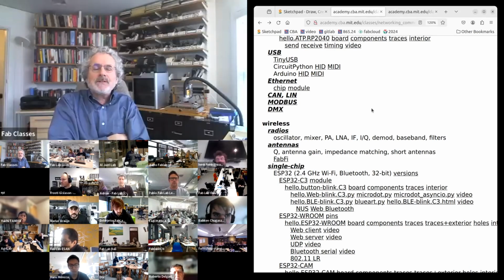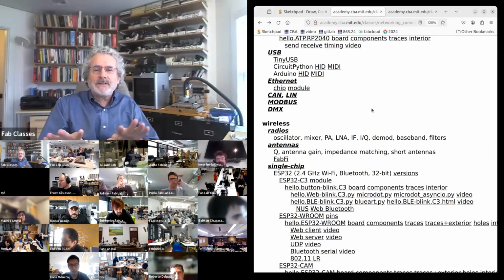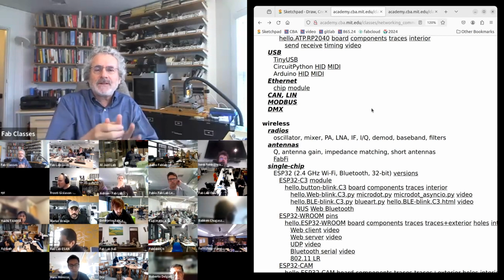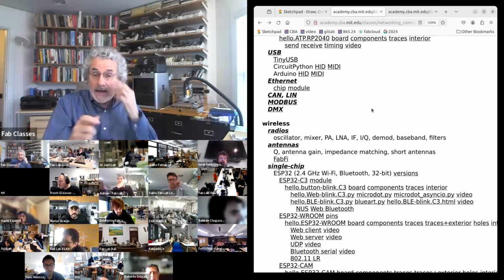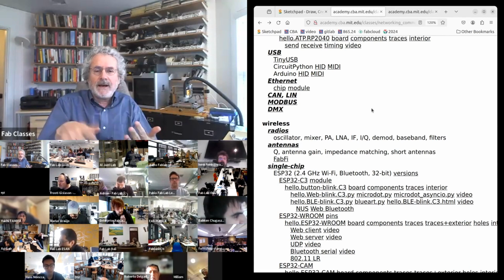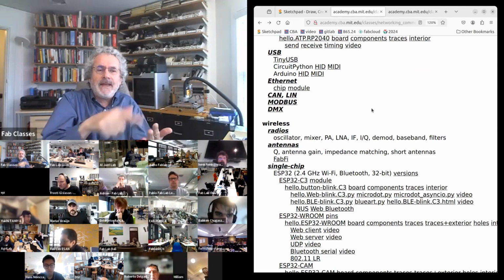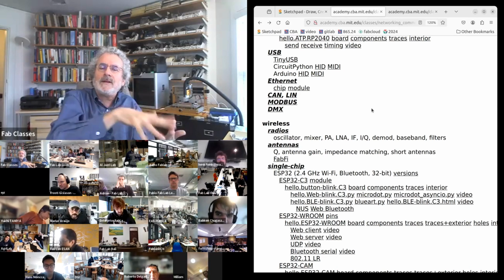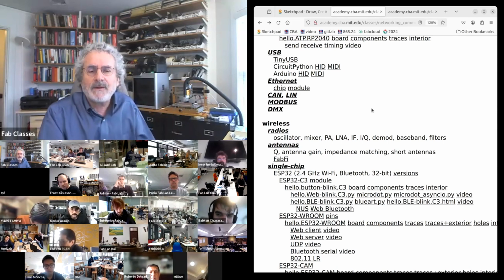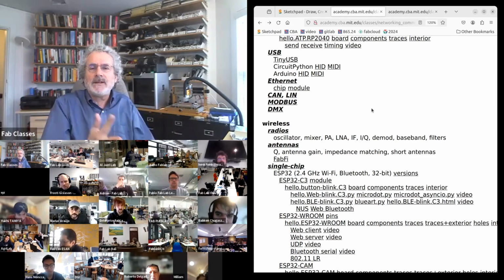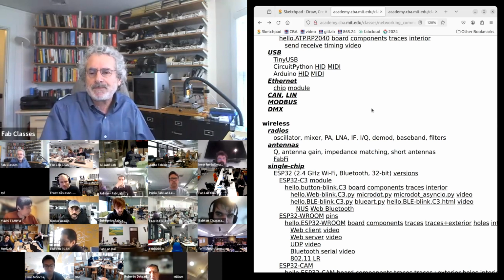Yeah, so this is what's called timing recovery, which is if you have, for example, a not very accurate clock and you're not sure of the clock rate, a more powerful processor can listen to the data, and from the data, it can figure out what data rate it's sending at. And so there is still a clock, but you can adaptively recover the clock.